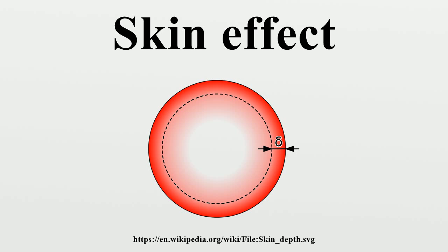A similar skin effect occurs at the corners of rectangular conductors, where the magnetic field is more concentrated at the corners than in the sides. This results in superior performance from wide thin conductors, e.g., ribbon conductors, where the effects from corners are effectively eliminated. It follows that a transformer with a round core will be more efficient than an equivalent rated transformer having a square or rectangular core of the same material.